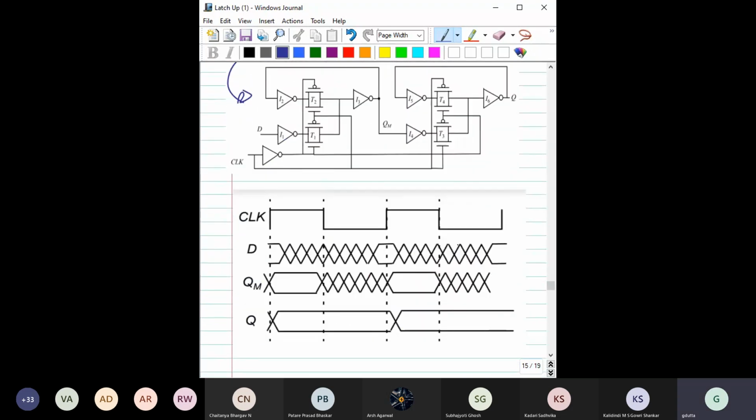see this one, you will understand from here. This is the clock input, right? And this is the D input, the data input. So the question is, during this positive edge of the clock, before that, for some time, this data has to be stable. Can you see this? The data has to be stable for some time before. After this clock edge also, this data has to be stable, right? Do you agree with that from this? Now, why so? We will discuss the reason.